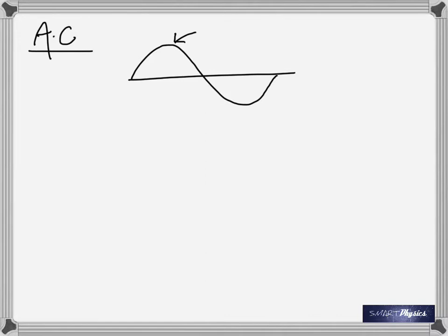But the current that these lines carry, they could be represented this way. Where on the x-axis you have time, on the y-axis you have the magnitude of the current. Isn't it clear that the current is changing? It's a sine curve. So the current goes from 0 to a peak value, back to a 0. And what is this? How do you explain that? I mean, in waves we call it a trough, but in electric current, what does that mean? It simply means it's flowing in the opposite direction. So all this time it's flowing in one direction, and here it's flowing in the opposite direction. Again it switches. That's why it's called an alternating current. It alternates directions. And how many times does that change? On these lines it changes 60 times in a second.